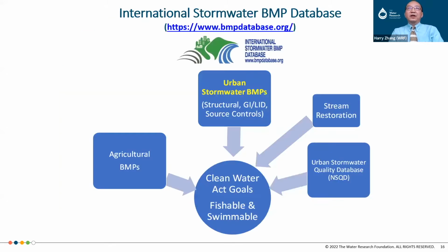You want to compare different scenarios in order to pick the best available scenario for your specific case. And for the performance, the tool connects to the International Stormwater BMP Database, which has been built over more than 25 years and holds rigorous BMP performance data. We have a team member who is an expert on the BMP database supporting us.